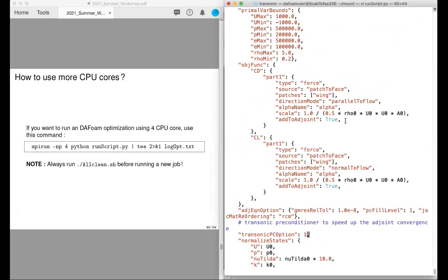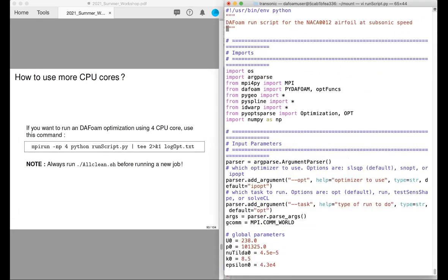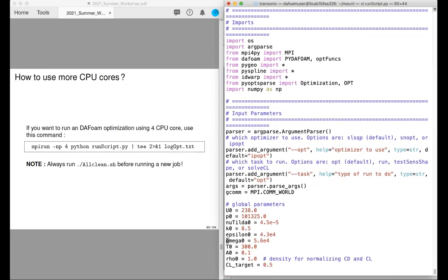Yes, I have a question. What is the omega that comes in all the solvers? The omega, yeah, it's a turbulence variable for the k-omega SST model. If you don't use k-omega SST as the turbulence model, you don't have to set this up. Okay. All right. Thank you.